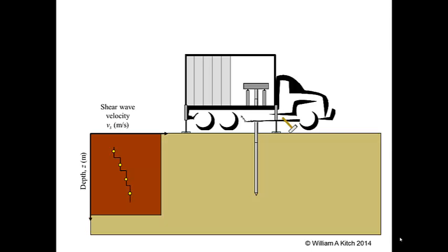One of the characteristics of the CPT is that it does not take soil samples. At sites where disposal of drilling cuttings is a problem, either because of the location of the site or because the cuttings may be contaminated, this can be an advantage. However, in general, this is a shortcoming of the CPT test. There are, however, ways to mitigate this shortcoming.